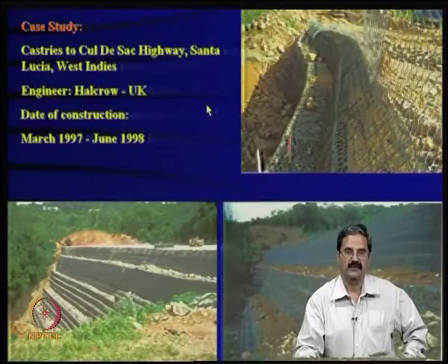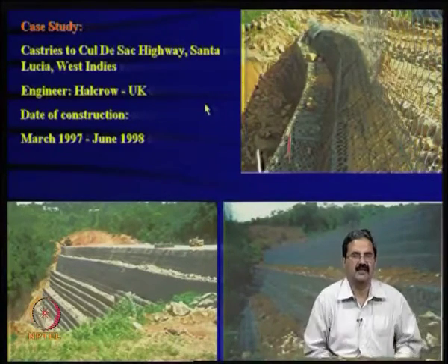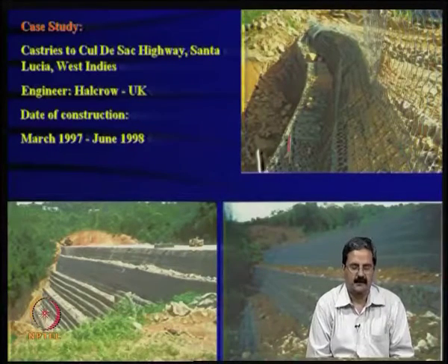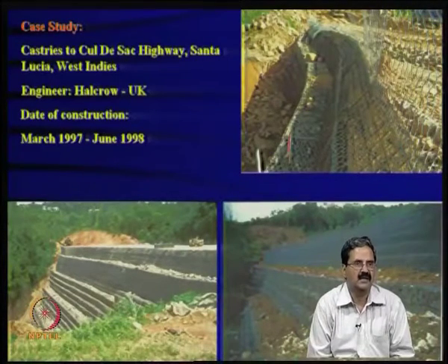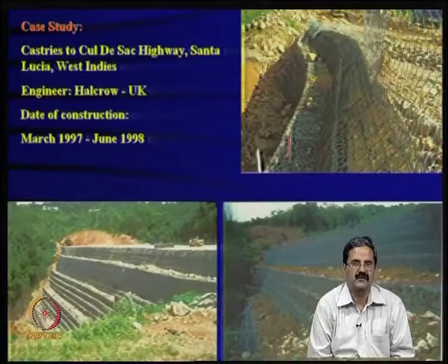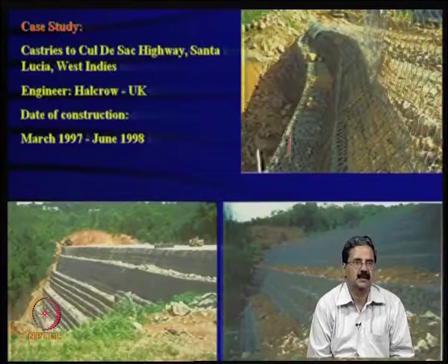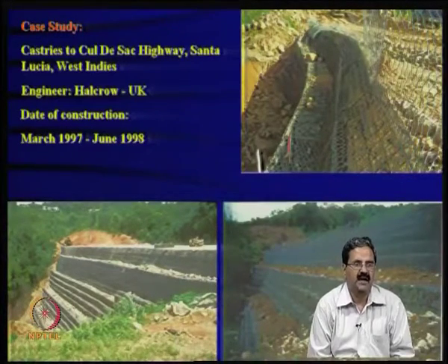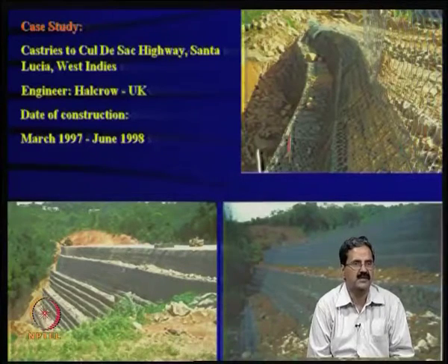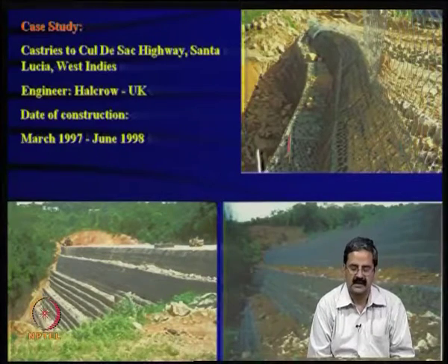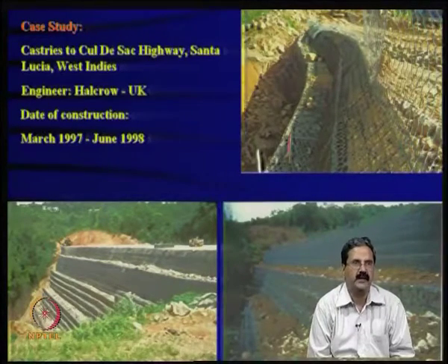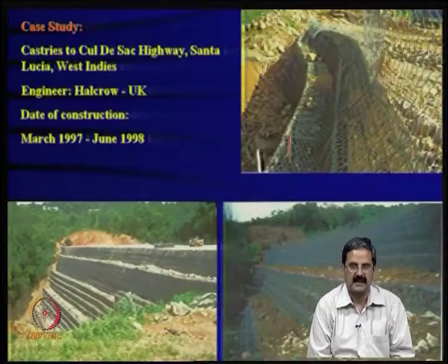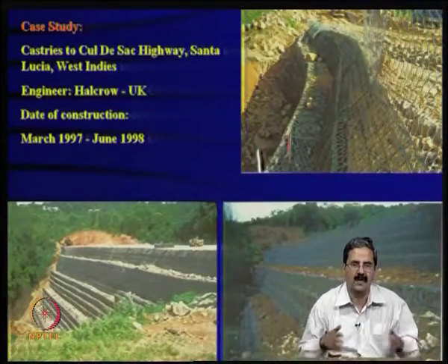And in fact, as I just mentioned, if you remember in the first class, Henry Vidal was the discoverer of the reinforced soil technique, and the first applications were in slopes, particularly in France, and they have been very effective. Even in the Himalayas you have a lot of slopes like this, and in many places people have been doing it very effectively, because particularly in hilly areas you want to widen the road.